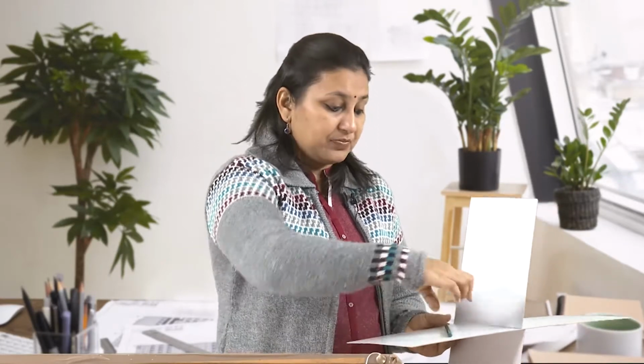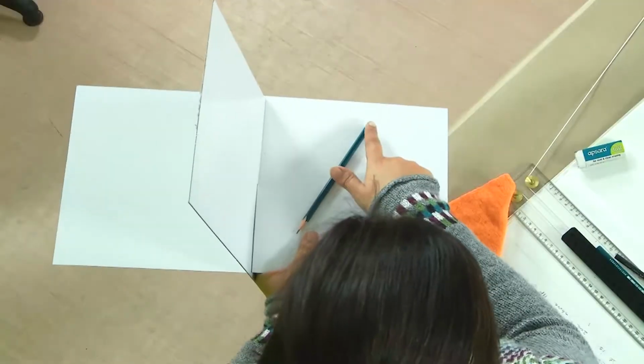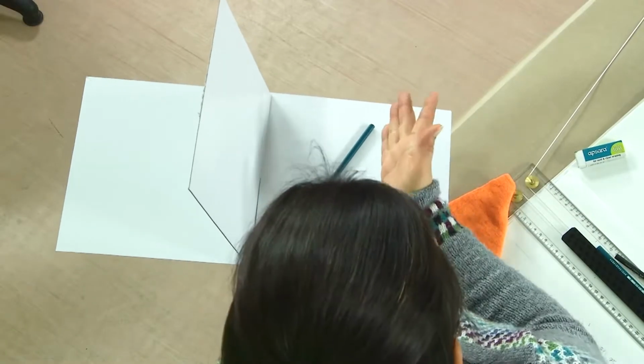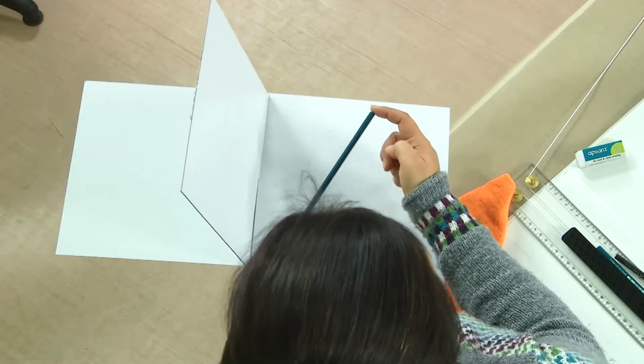We can understand it in the reverse manner as well. Imagine that this line is parallel to HP and it is making an angle of, say, 30 degrees with VP, which is the final angle. Now, we have to move this line in such a way that it additionally makes an angle of 45 degrees to HP as well. And how do we do that? In that case, we will move it not like this, but in such a manner that the distance this point has from the XY continues to remain the same. So, we move it like this.